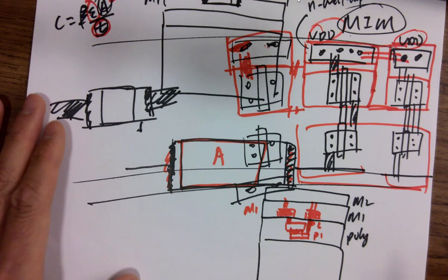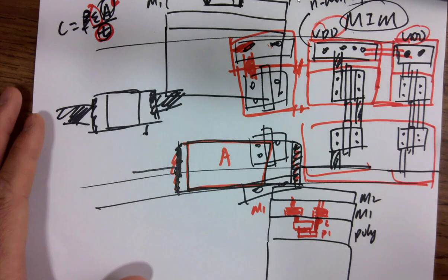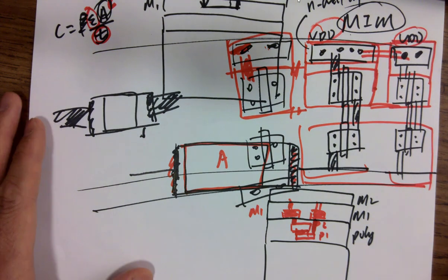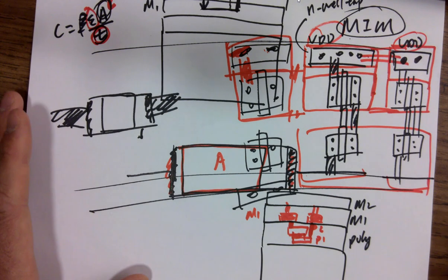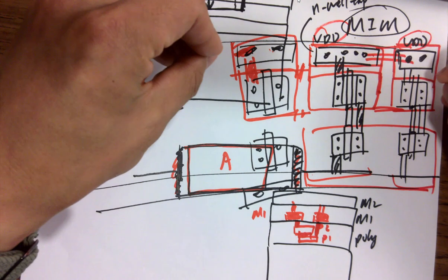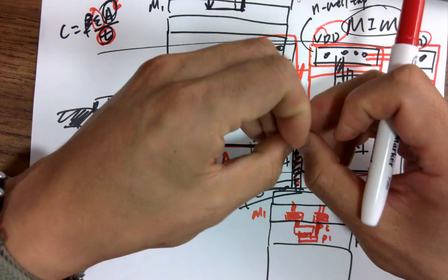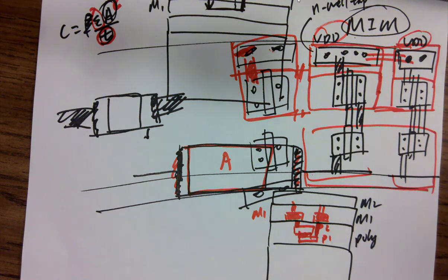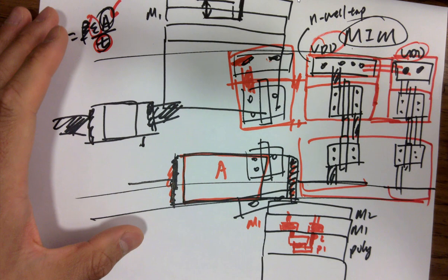So when you are doing the layout, you just draw a capacitor next to it, which is fine. Then you just label the metal layers and connect them with certain traces. I won't be super picky on the labeling of the layers for the metal traces, because there will be a lot of connections, and you are trying to avoid short circuits within that little area. You probably don't have different color pens with you, so I won't be super picky about the wiring. But if you can label that, it would be great, so I understand what you are doing. I can give the credit on that.